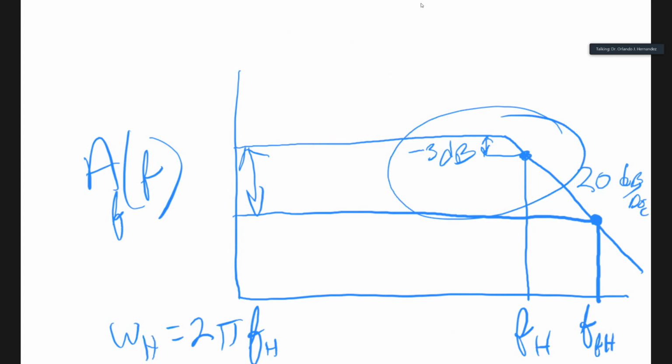So this slope here gives you that gain bandwidth product. So you can see your gain goes down and then the bandwidth gets extended. So you get this extension of bandwidth by this reduction in gain. Okay?